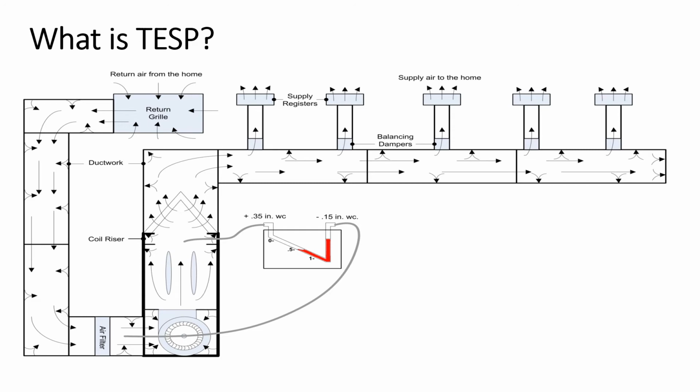So once again, the ductwork is going to give us a resistance to airflow and give us a static pressure amount. Our comfort cooling or heating coil is going to give us that resistance, as well as our takeoffs, our pipe, our registers, or diffusers are going to give us a certain amount of static pressure. And that's what we want to measure right at the breech or the outlet of that piece of equipment. That way we can accurately measure in inches of water column the static pressure of all those components added together.